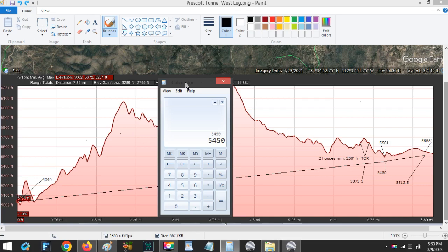the grade profile differs from the grades you get from ticking that terrain box in the left panel. And the grades that you get by hovering over the imagery are more accurate than the ones in the grade profile.